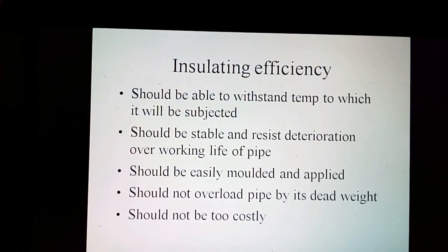It should be able to withstand the temperature to which it will be subjected. It should be stable and resist deterioration over the working life of the pipe. It should be easily molded and applied. It should not overload the pipe by its dead weight. It should not be too costly.